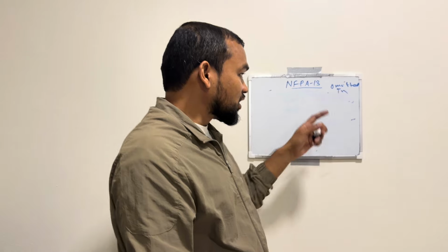In a dwelling unit, we can omit the sprinkler in certain small, low-risk spaces, where the areas show very little fire, low fire loads, and minimum fire risk, like a bathroom. We can omit the sprinkler in a bathroom in some conditions: the area is less than 55 square feet, located inside the dwelling unit, and all walls and ceilings are non-combustible or limited combustible. So in this case we can omit the sprinkler in the bathroom of the dwelling unit. An additional allowance is a bathroom under a stair, which does not require a sprinkler.